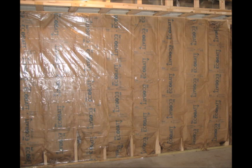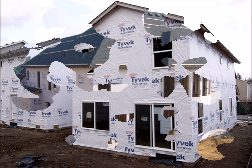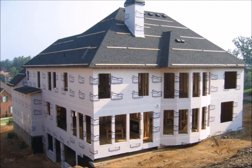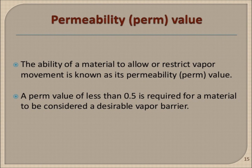When a home is built new or an existing home has an addition put on it, we use Tyvek, officially known as house wrap. This material allows some moisture or vapor flow while stopping both liquid water and air. Different grades of house wrap have different properties. When discussing vapor barriers, we also call it drainage planes. The measure of water vapor permeability is called the perm.